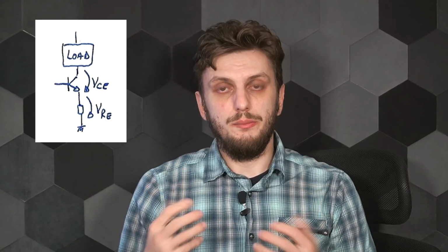Now the circuit works, it's performing as expected, but there are some interesting things to point out regarding what could have been done differently, specifically regarding the efficiency. The main non-ideal elements which are pushing us away from the maximum theoretical efficiency are the minimum collector-emitter voltage not being 0 but rather a couple volts, and also the voltage drop on the emitter resistor.